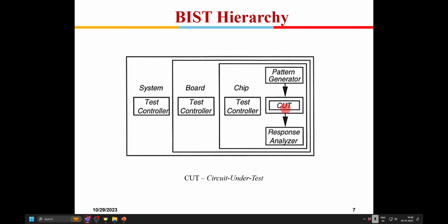Like for example, in a memory design, when a memory test is run, there is a possibility, like now you have some terabyte memory, right? So while doing the test, if say one sector of a few megabytes of the memory is faulty, you don't throw away the entire memory chip, right? It would be such a wasteful use of the resources available to us. So there will be a provision to isolate that particular sector of a few megabytes of the memory which is failing when you are doing the March test. Okay, and the result is failing.